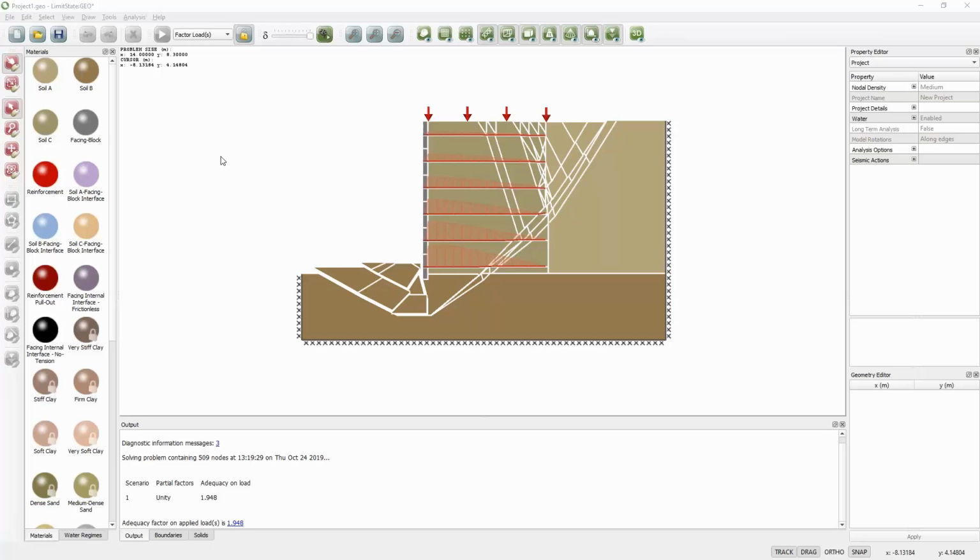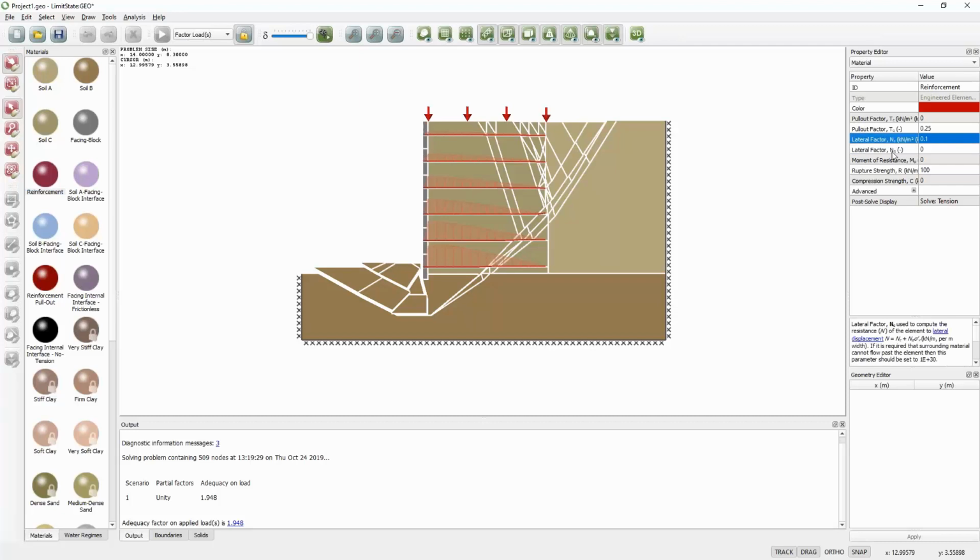So rather than piles to take a load from a structure. And then if you're reinforcing a slope, again, you can just calculate in the same way the resistance to soil moving past the pile. And this is where I think these lateral values would start to become significant, because that's the main purpose of a pile that's used to reinforce a slope, that you're looking at the lateral resistance. So you can represent those piles by these one-dimensional elements and still get the two-dimensional slope stability analysis.